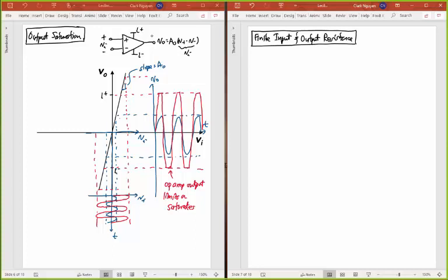The op-amp, if it's ideal, would love to have an infinite input resistance and a zero output resistance, but in reality you don't get that. So if I were to really draw my op-amp model, I would have to draw something like this. Okay, so I'm going to draw a big op-amp here, basically. And so here's one terminal going in. Maybe that's my minus terminal. That's going in now. Instead of to an open circuit, that's going into a finite resistor. And that's my resistance Ri. Let's call that V plus there.